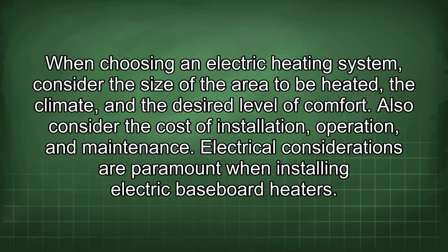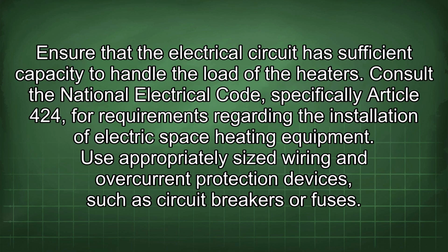When choosing an electric heating system, consider the size of the area to be heated, the climate, and the desired level of comfort. Also consider the costs of installation, operation, and maintenance. Electrical considerations are paramount when installing electric baseboard heaters. Ensure that the electrical circuit has sufficient capacity to handle the load of the heaters.